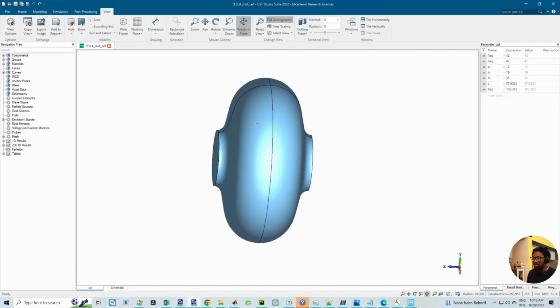I'm going to use the eigenmode solver, and then you have to export the fields to the particle in cell solver, which is a time domain solver, and that supports only hexahedral mesh. You could do it with tetrahedral mesh, but it's not very ideal. I tried once, but I think there was a problem with the results, and I concluded without looking further that it must have been because I used tetrahedral mesh, because in the end the results would have to be interpolated onto the PIC solver.